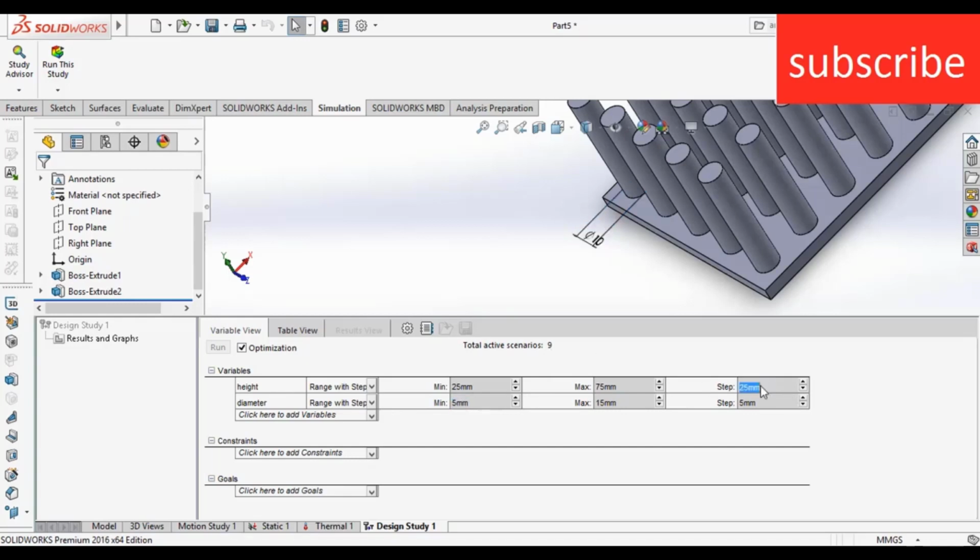So let's change the value to 10. Here you can see the total number of active scenarios. Remember, the higher the active scenarios, the better chance you get of a result, but the more time it takes. So I'm going to increase this step value so that my total active scenarios get reduced. As you can see, it is now 15. I am reducing it more to 20 mm because it is just a waste of time for me. The main aim here is only that you learn how to do simulation. Now let's see another thing.